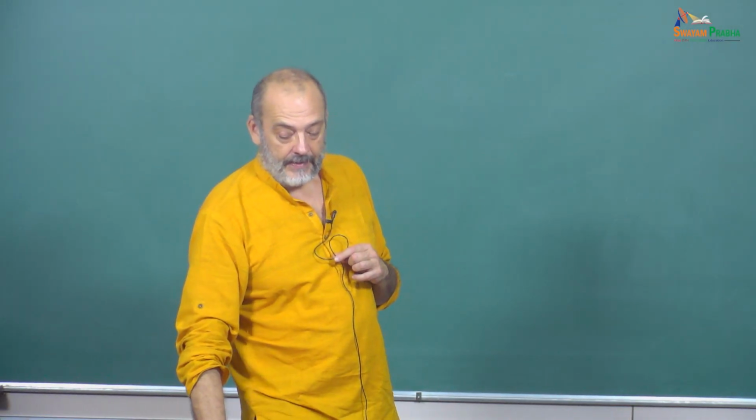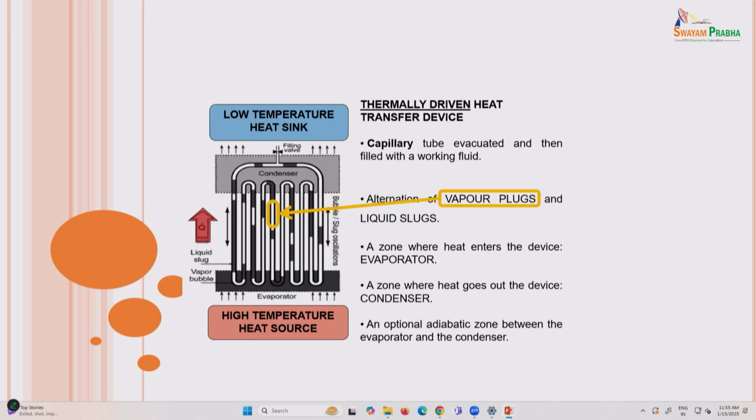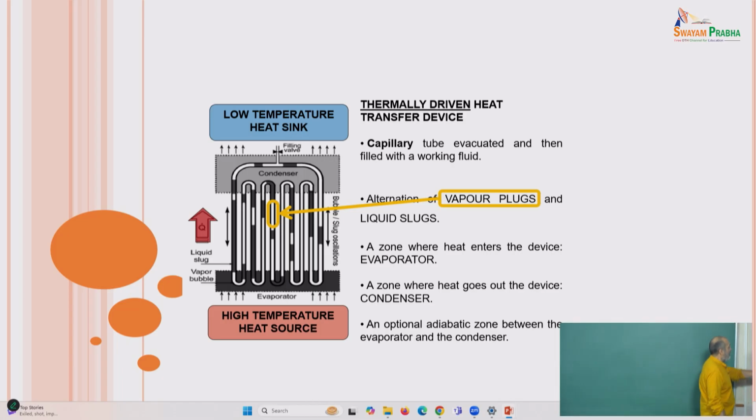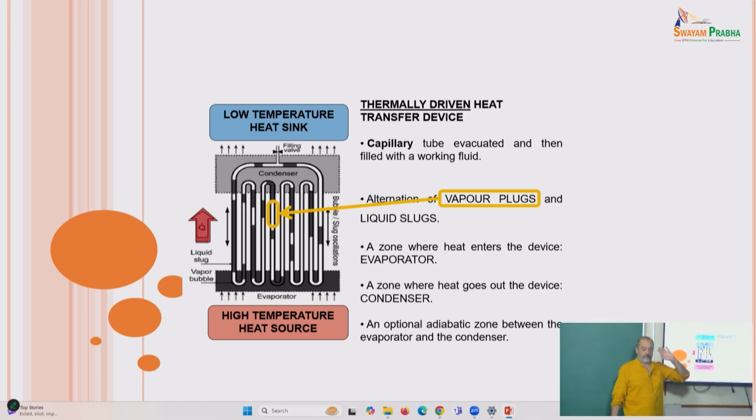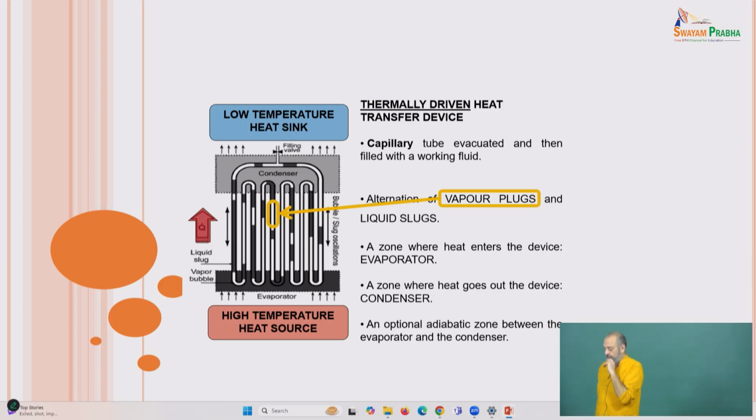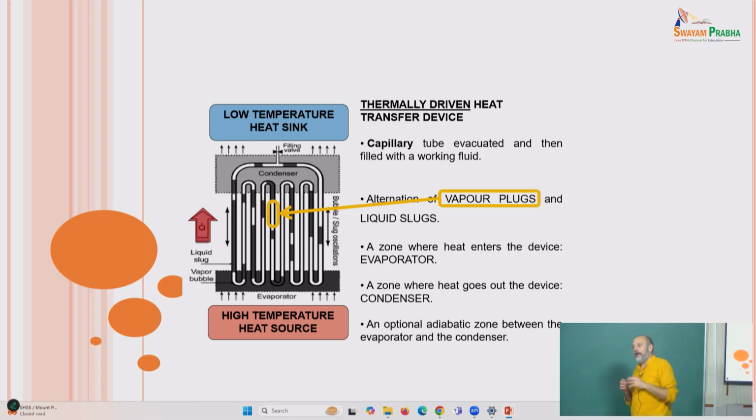For the pulsating heat pipe, the pulsating heat pipe is a system where, as I already said, we are going to fill the system. For all the systems, I didn't say that. I need to remember. I think that you know, but it's better to say that we are not, of course, filling a heat pipe completely with a liquid. We always have a fraction of the volume inside that has the liquid at the beginning, okay? This is the so-called filling ratio.